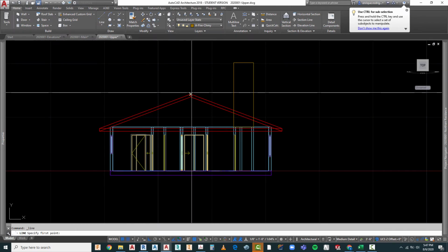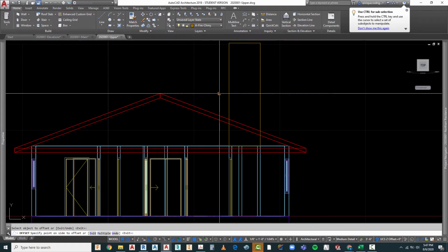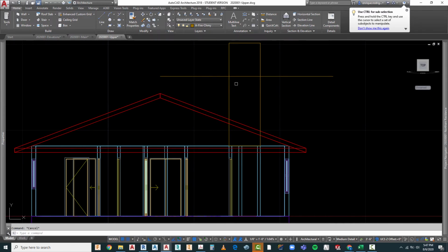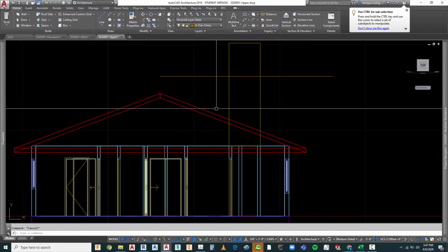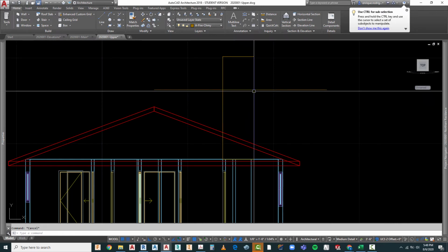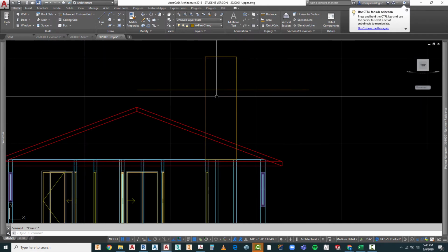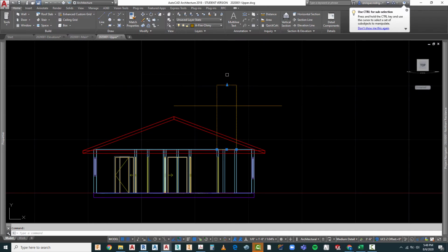Now the minimum height that this should be, I'm going to go ahead and offset this 2 feet. Usually there's a code because of fireplaces where the top of the chimney wants to be a minimum of 2 feet higher than any point on the roof 10 feet away. I think this is going to be sufficient. That would mark it from the peak, which may be more than 10 feet, but I think that's going to look pretty nice, and then we can add trim work on top of that. So how do I get this point?